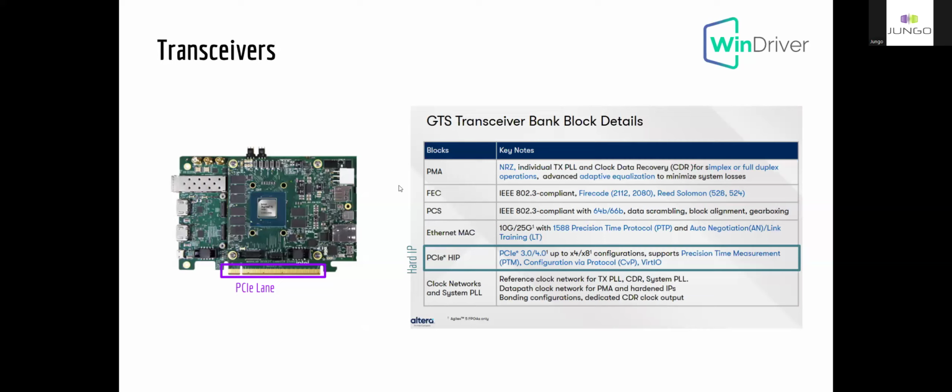And this is just an example of what an FPGA essentially is. It allows you to add different blocks to your design. And here we have a hard IP of PCIe, so it is 3.0, 4.0. You can see the speed, you can see the features, and we know that it is embedded on the device already. You just need to add it in order to activate it and use it, and it will use the FPGA PCIe lane, the default PCIe lane that connects it to the computer.